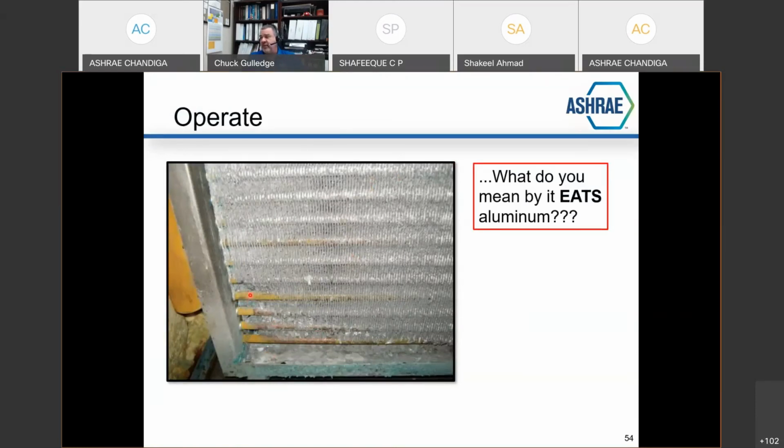This was a life safety client, and they deal with blood pathogens. And they use, and I won't name it, a special product to clean surfaces to deal with the fact that they do have blood, and you worry about pathogens being transferred around. And this chemical that's used is aggressive to aluminum. So when it gets in the airstream, especially when somebody steps inside the air handler and sprays it on the coil, look what happens.